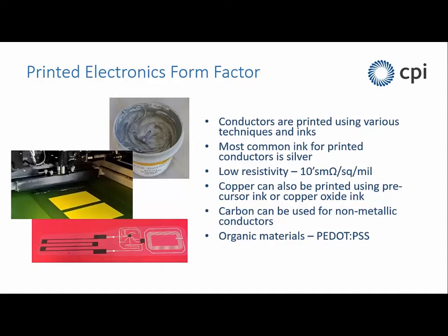Or if you're trying to do maybe inkjet printing, then you need a very thin, easy to jet material. So the rheology of the inks is a critical part of their assembly. All of these inks come up with relatively high resistivity. If you're electronics designers, you know that we use copper for most printed circuit boards, and the copper that we use is probably what's called half-ounce copper, typically about 18 microns thick of real metal. That's 100% metal pretty much you've got there.